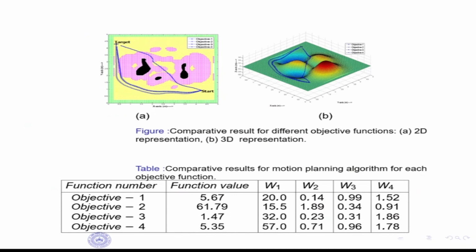Now, it is saying that W1, which is the attractive force, is the highest value that is expected. So, on this 3D terrain, when we ran the GA algorithm to find the weights, we found that the weight W1 has the maximum weightage. Okay, it is because it has to attract the force, and the next is the gradient force. Then the third is the lowest value, the repulsive force, and then the tangential force.